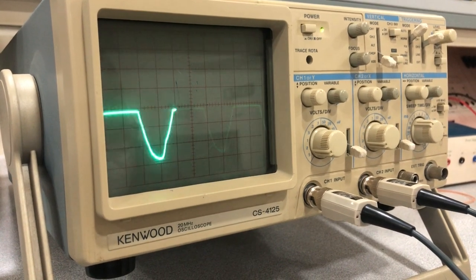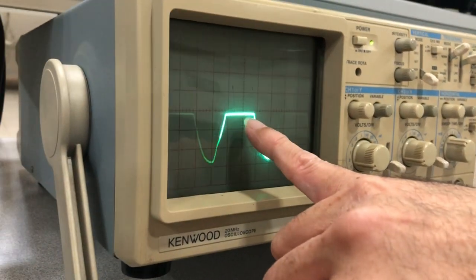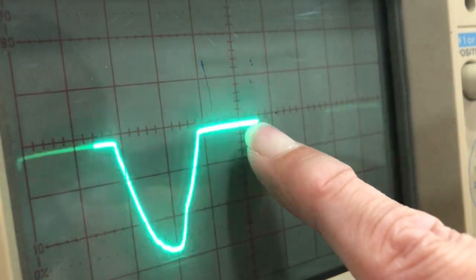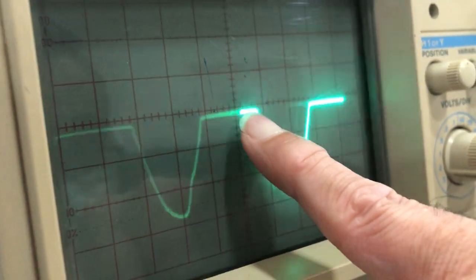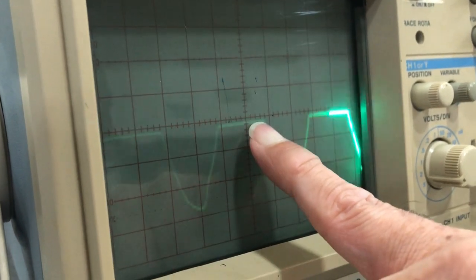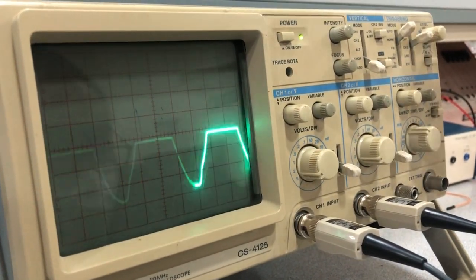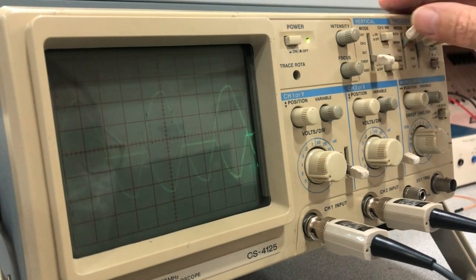And what does that tell me? Negative cycle. I have this horizontal line here which is minus 1 volt approximately, but a bit less, maybe around 0.7. I want to see it better. Or let me see the two peaks and measure the difference between them. This is one way. Go back to both channels.